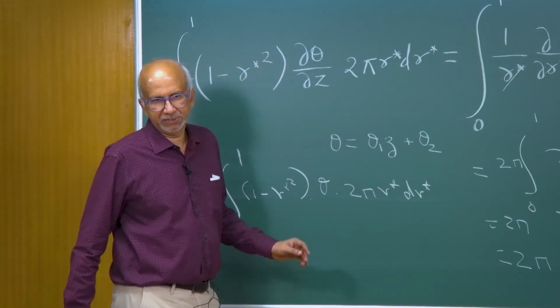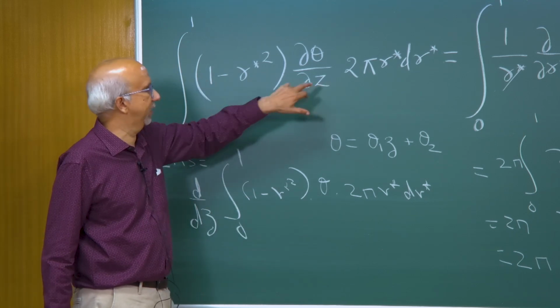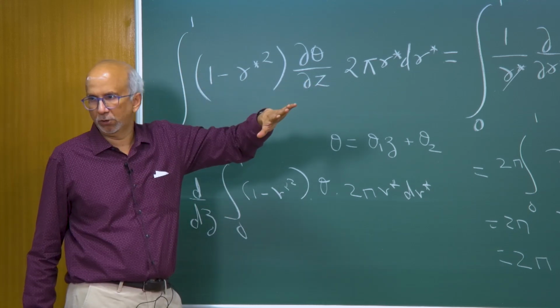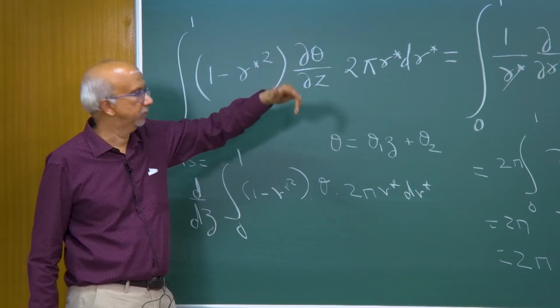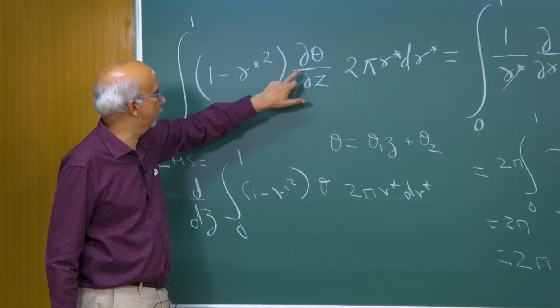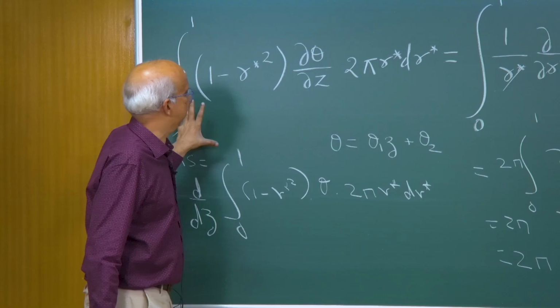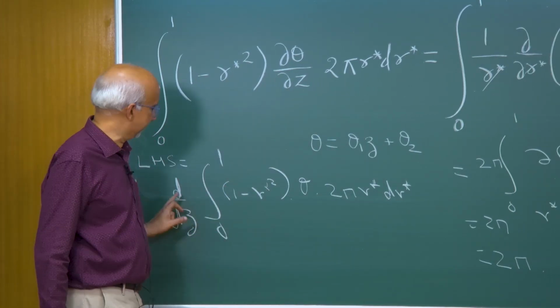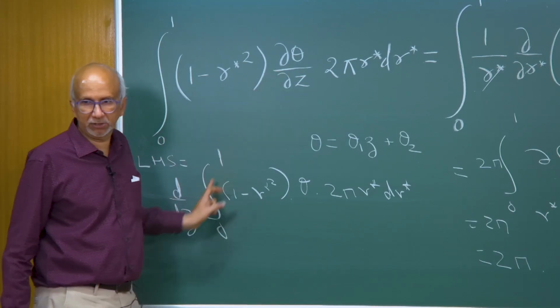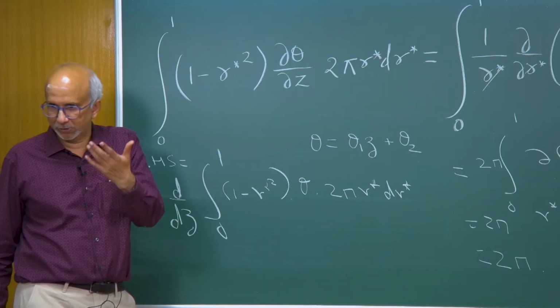So, let me just recap. This is just the energy balance equation which we wrote. We have integrated this in the r direction, and all I have done is substitute and recognize that this is a function only of z, because I am integrating in r. So, now the partial derivative has become the total derivative, because after integrating in the r direction it depends only on z.